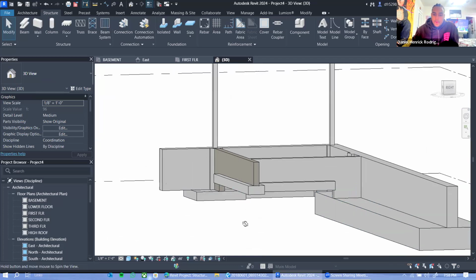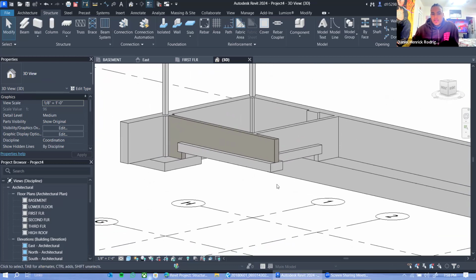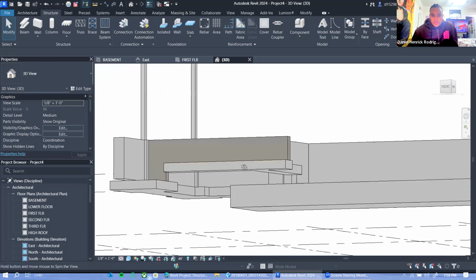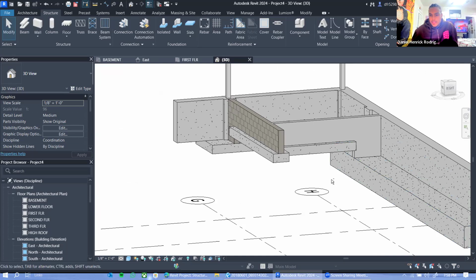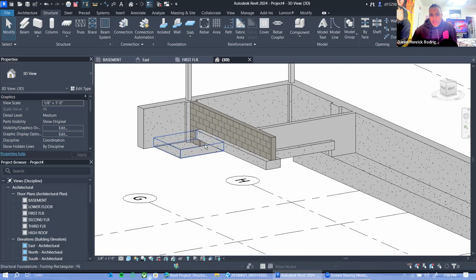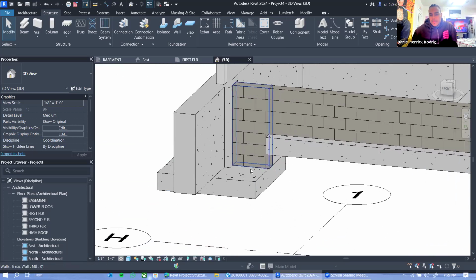Because of the level of the street and what type of soil is below the building, you're going to have different depths that the foundation goes to so that it can be on good strong soil that will hold the building. So this foundation is actually going to be a negative 2A, while these on the outside are a negative 4A. And that's why this one is higher. And that's what this footing step looks like.